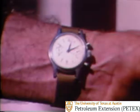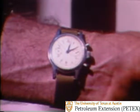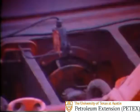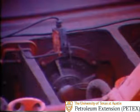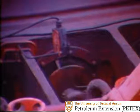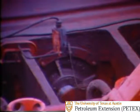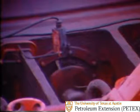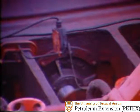Over-control resulting from not taking this delay into account has been the cause of many failures to handle a kick properly. For it must be remembered that the pumping rate must be maintained at a constant speed. However, the pump can be stopped and the well shut in again at any time without danger, so as to permit new observations of shut-in drill pipe and casing pressures.